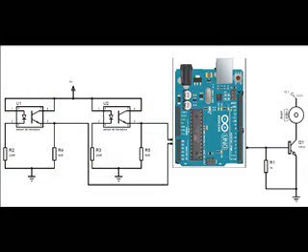The circuit that we use for the infusion pump consists of the connection of each sensor and an electric power stage for the motor, because this one requires 15 volts to work and to generate enough force to impel the water with the rollers through the hose. To achieve that, we use a TIP31C, which is a bipolar power transistor.